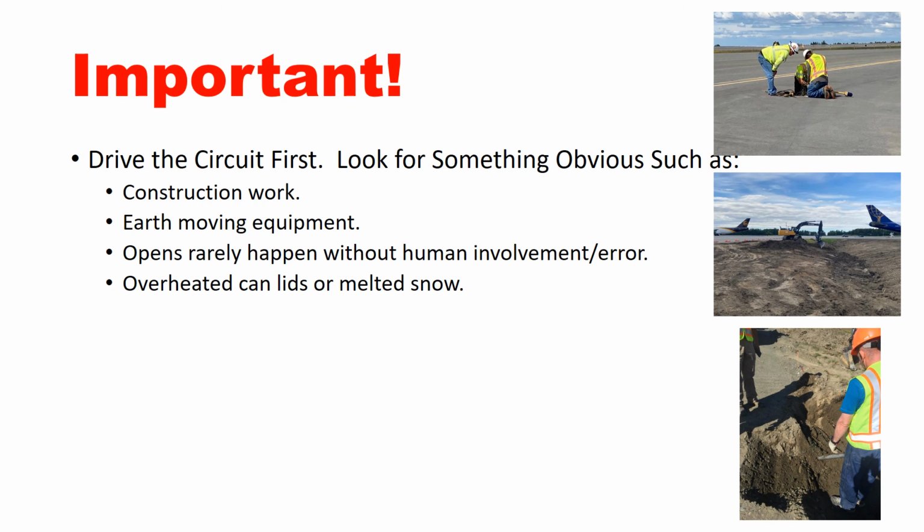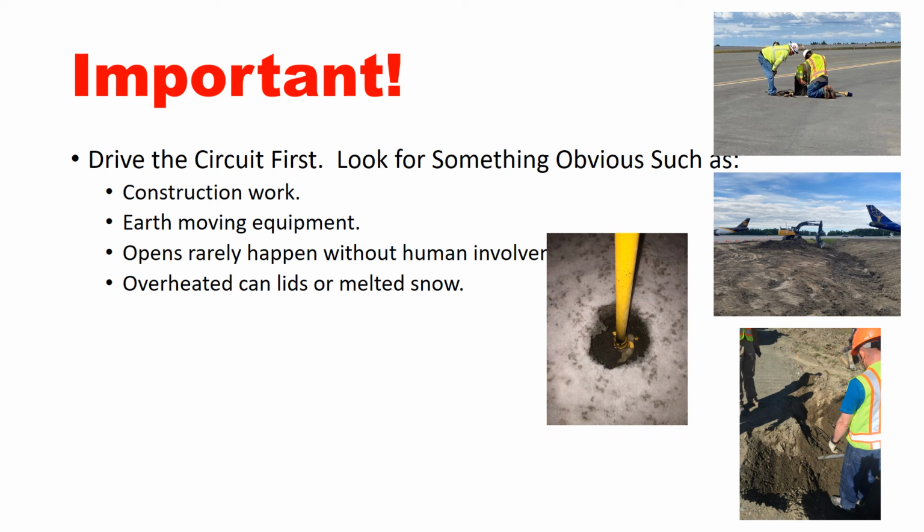Now, another good thing to look for is overheated cans and lids. You can go out and drive the circuit, especially in winter. Look for melted snow on a lid, and that could be a telltale sign, and it can save you a lot of time.